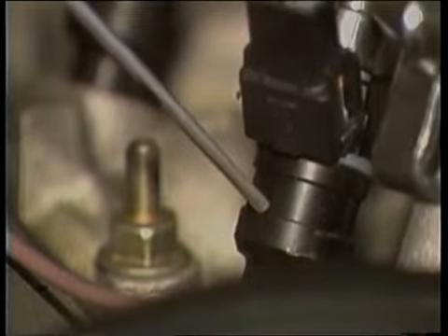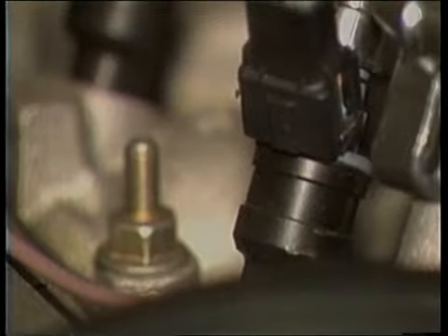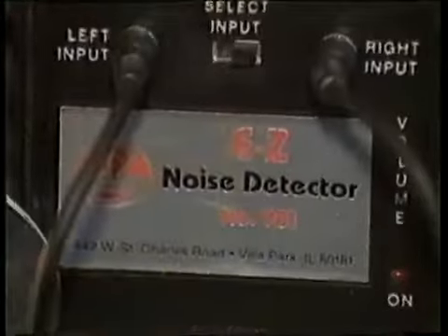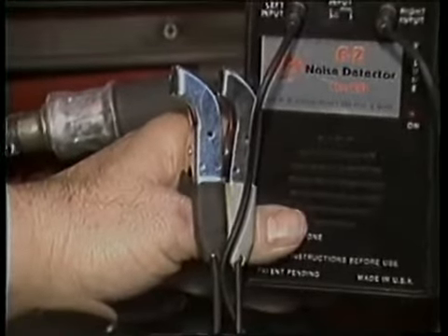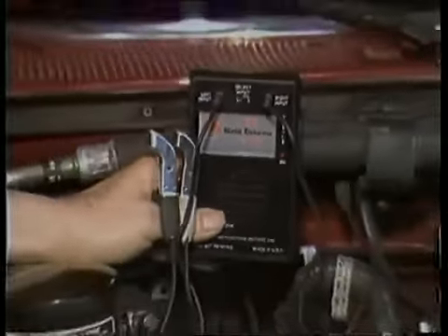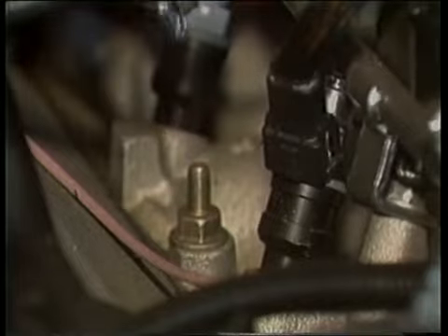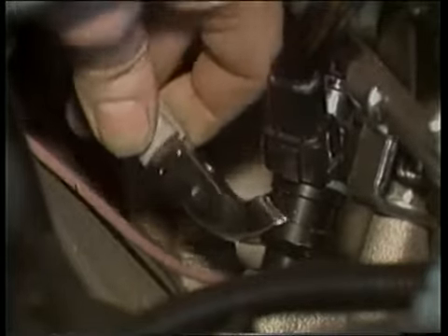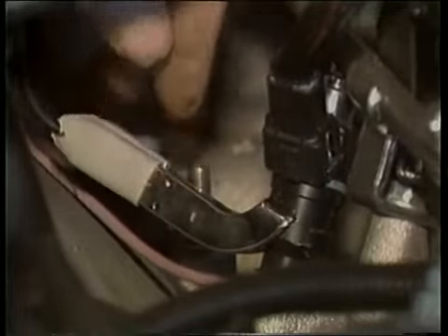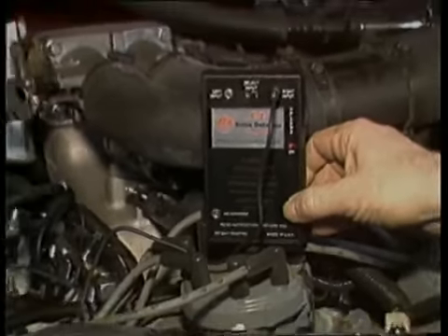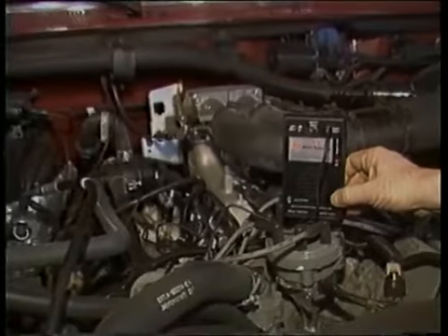With the metal prod back on the stethoscope, you can listen to the inside of an injector. If a miss indicates that one cylinder in the engine is dead, you can listen to make sure that each injector is firing. An electronic stethoscope provides an even better way to listen to the injectors opening and closing. This unit has large clamps that are attached to the components being tested. The amplifier and speaker will then produce loud sounds to show injector operation. This is a quick way to make sure that a computer pulse is reaching the injector and that the coil inside the injector has not completely failed.